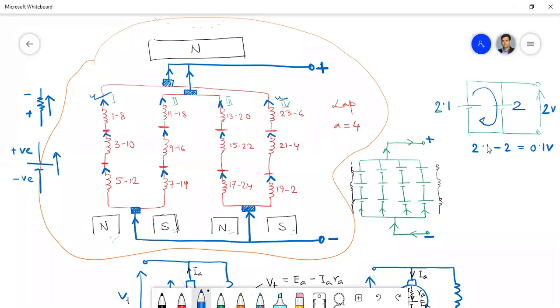Now, in this circulating path, what is the impedance? The impedance is very low. The internal resistance or impedance of the voltage source is purposefully kept very low. Now, if this 0.1 volt arises in this circulating path, then that 0.1 volt is sufficient to make a huge amount of circulating current flow in this path, isn't it?